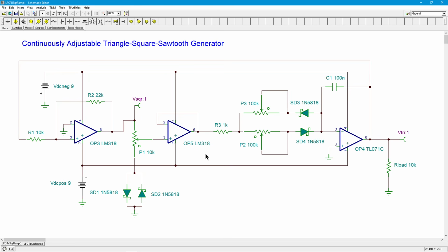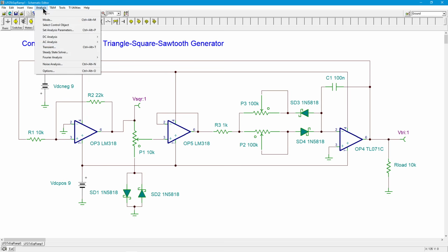Like I said, it's just a simple op amp. And you'd use the same kind of op amp. You still want the speed out here to keep your square wave coming out. Pretty nice. This would be the full amplitude square. You theoretically could tap out here, but I wouldn't recommend it because this is isolated with the buffer. All right. Okay. Let's take a look at some output waveforms.